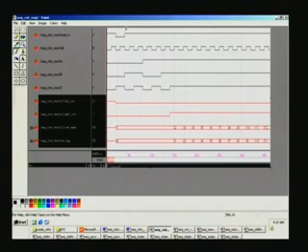When a reset occurs, irrespective of the clock edge, you clear the counter as such. This counter reg is here, it is cleared to 0, and you notice that counter next is incremented by 1 right here. This is what I meant by pre-incrementing.